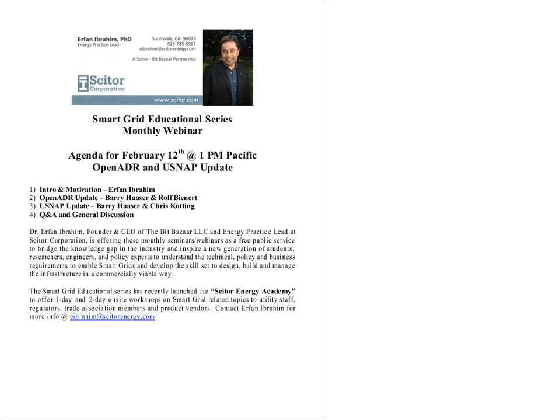Okay. Next question is, are OpenADR devices registered with a central authority? I say yes, because the OpenADR security certificates are registered. The devices themselves are not necessarily all registered, but the way we distribute security certificates is through a central distribution node that is managed by the Alliance together with a vendor. Any certificate authority out there can become part of the program by implementing the certificate policies and then going through an audit to be part of the OpenADR security certificate system. So all these certificates are registered, of course. Not each device per se, but the security certificate is.